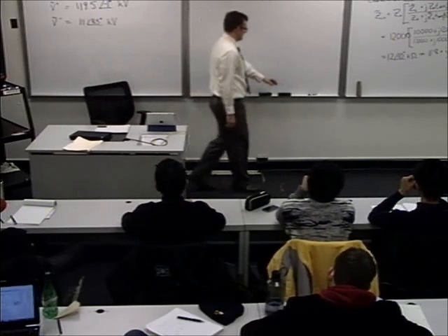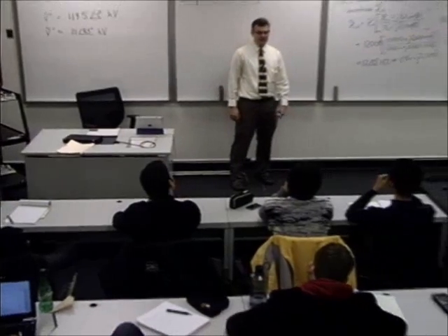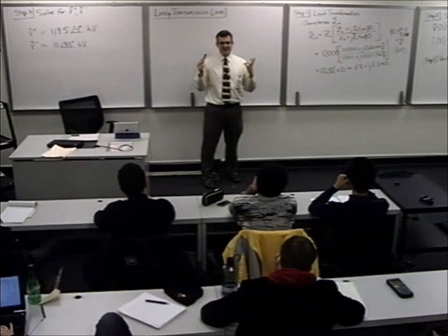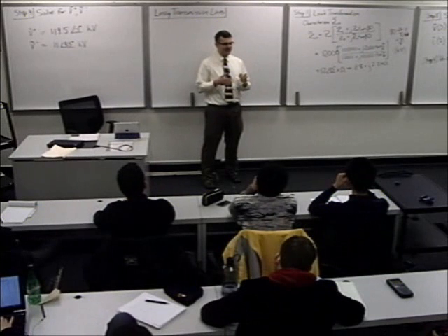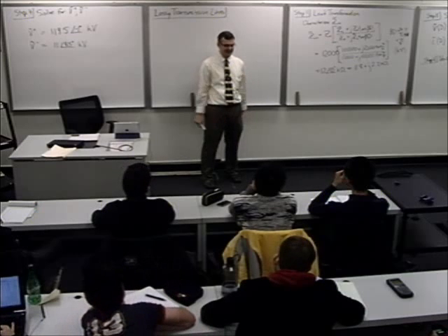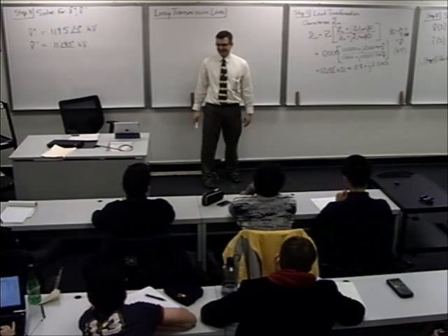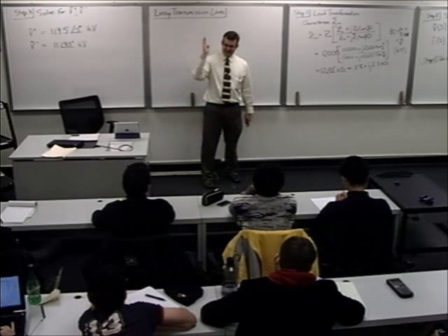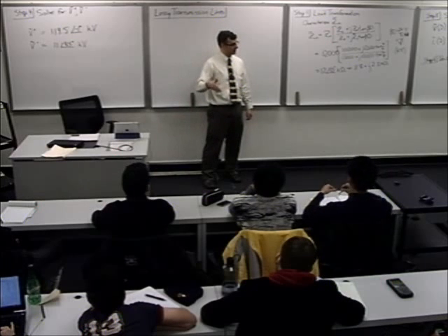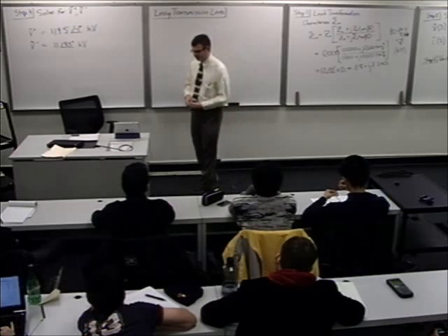So that was one aspect, regenerative repeating. The other thing that we're going to learn today is that the transmission lines get exponentially lossier as you go up in frequency. So there is actually a big difference in loss when you go from a telegraph signal, which is in the tens of hertz, to a voice signal, which is in the kilohertz regime. That's several orders of magnitude of both frequency and, it turns out, also loss per unit length of cable. And that's what we'll talk about now.